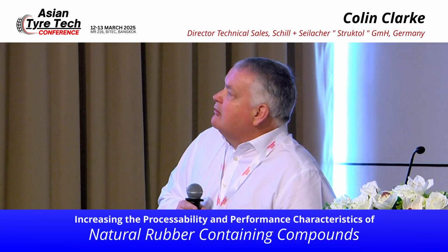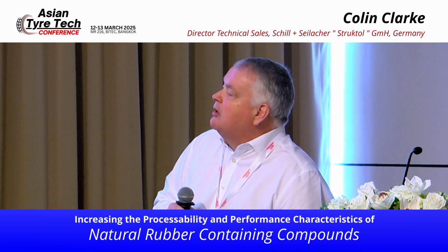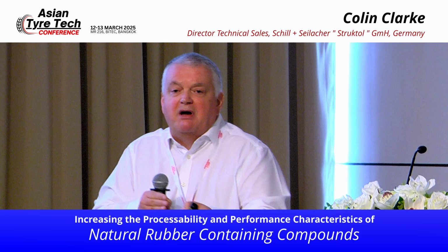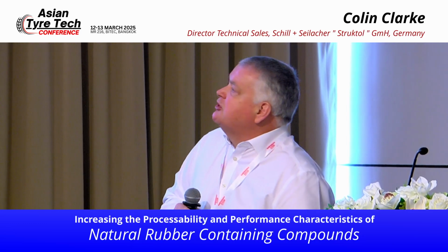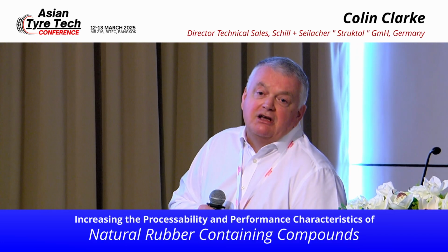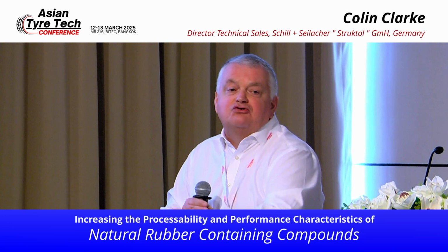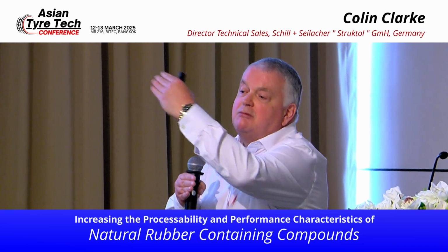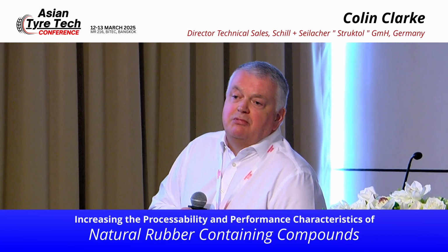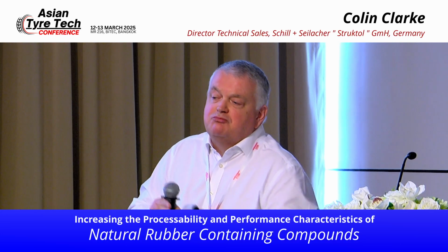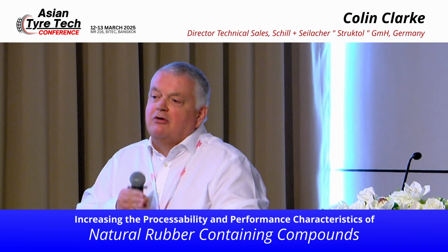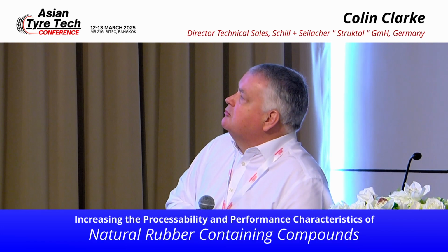If we index the control compound, with no peptizer at all, 3.5 minutes: as we increase the mixing time, because of better breakdown and dispersion, for sure we reduce our hysteresis, we reduce our tan delta. But by contrast, the chemical peptizer actually increases that hysteresis. We generate a lot of short chain material and branched polymer, and our heat buildup potential in the natural rubber increases. The new product gives us the lowest heat buildup of all. Not only do we have the lowest Mooney viscosity, best flow properties, best extrusion, we actually have the coolest running compound, lowest hysteresis, best energy saving performance.